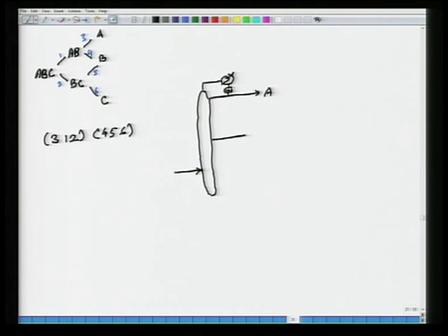All right. So this tower is providing liquid to the other tower. What does the other tower do? It's got its own set of 3 subsections, or tray sections, and this is my ABC feed. I've got a reboiler there which corresponds to section 6.